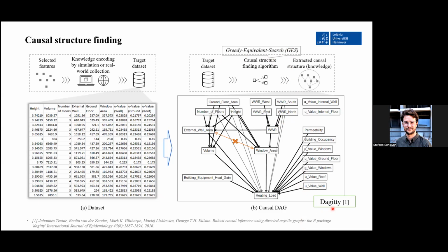What is the benefit of having this relationship automatically determined, given that we already have a good physical understanding of those, and usually the unknown parts are maybe the coefficients that we input or some other parameter that we may not be sure about how to model, for example, occupant behavior. On the opposite, the effect of window area or the U value of the windows on the heating load is kind of clear. And for some other aspects, for example here, there is no differentiation between the different orientations, when we know that the importance of, for example, the solar heat gain coefficient will depend on the orientation. It's very important on the south side. It may not be important on the north side. So I'm wondering why you chose this direction of modeling.